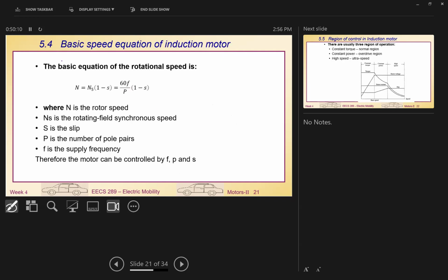So again, that's a really basic equation for motor drive. You can see that we have something called the frequency here, and it also relates to the number of poles. A motor with 2 poles is the basic motor; at 60 Hz, the rotation speed will be 3,600 RPM.